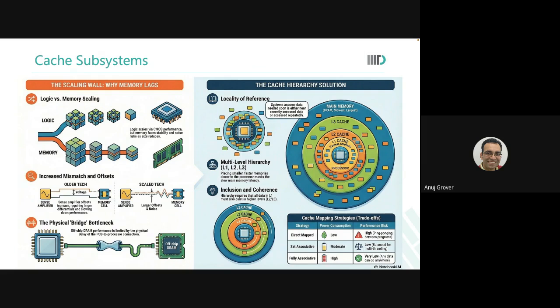What is the impact? How do we see that? The access time increases because of the larger block, but the probability of missing, P miss, will reduce. But along with that, the access time will also. Will it reduce monotonically? No. So the probability of miss will initially reduce. If my line length was only 1, then after the first miss, I'm expecting a second miss and a third miss and a fourth miss.